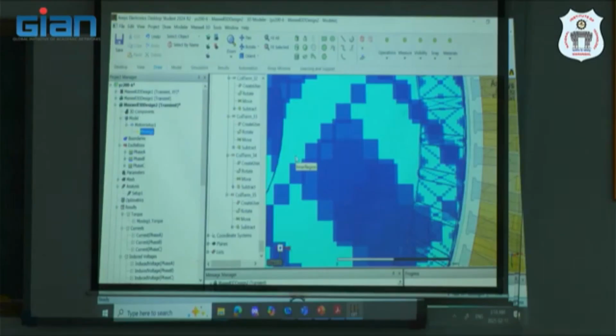But what I am trying to say here is, to learn the software itself, it will take you some time. But once you have acquainted yourself with the software, there are so many video tutorials nowadays from the supplier. You can also find on YouTube there are different individuals doing tutorials. Once you have acquainted yourself with the software, modeling a motor and introducing eccentricity fault is going to be way easier than the other approach of modeling a motor using coupled circuits and introducing eccentricity fault mathematically. Okay. So that is the big benefit of finite element simulation.